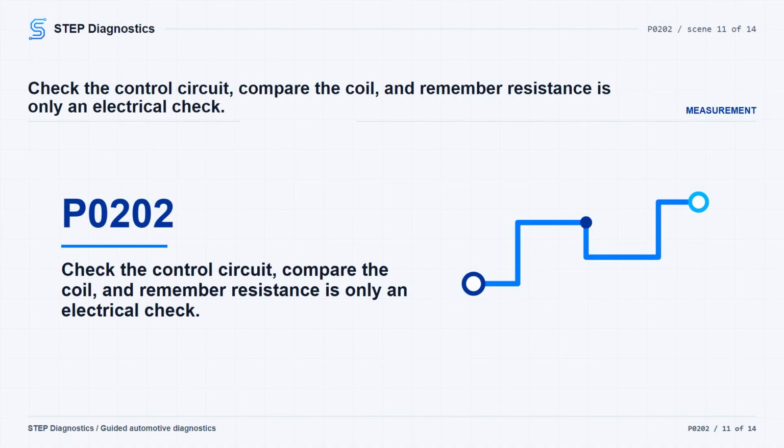Measure injector coil resistance and compare it with the other injectors if technical data is not available. Fuel injector resistance is typically between 9.0 and 18.0 ohms, and the difference should typically be less than 10% between injectors. Keep in mind that coil resistance only checks the injector electrically. It does not prove the injector is moving mechanically. That takes the scope pattern.